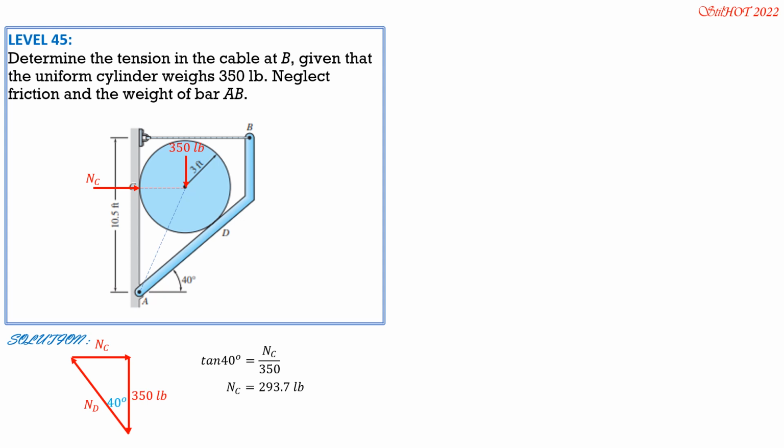And because this is a 90-degree angle equal to this angle here, in other words, this is the radius, this is the common hypotenuse, radius, common hypotenuse. So therefore, this 50 degrees must be bisected by this line here through the center of the cylinder. So each is 25 degrees, 50 degrees divided by 2.